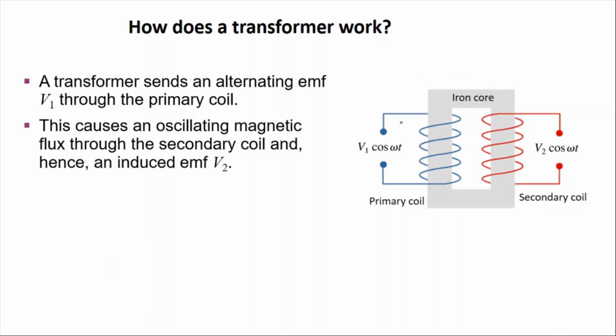So when a current is flowing through this circuit, it will produce some magnetic field lines, and the magnetic field lines are going to be something like this. We will have many magnetic field lines like this. So there is a changing current, and it produces a changing magnetic field, and the changing magnetic field is producing a changing flux here, and this flux produces some secondary current in the secondary coil. This is all because of Faraday's law of induction. You can go to our previous videos to see how Faraday's law of induction is explained.